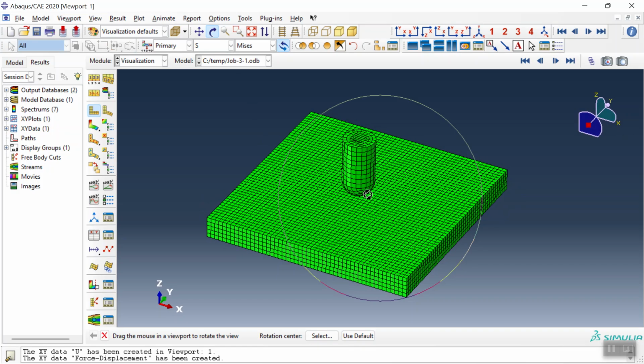In this simulation, the brittle cracking material model in Abaqus Explicit is used to simulate the cracking behavior of the reinforced concrete slab subjected to the impact from a rigid or a steel hammer. The main purpose of this material model is to represent the initiation and development of tensile cracking in brittle materials such as concrete. Unlike a conventional elastic material, concrete has a very limited tensile capacity.